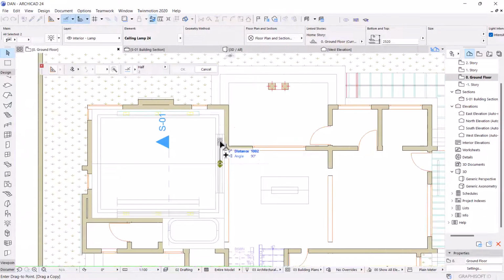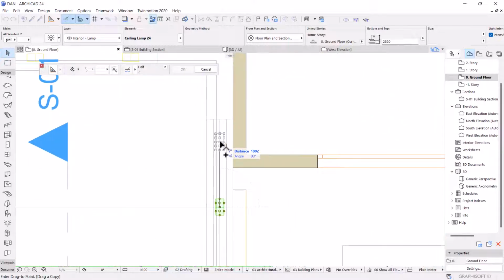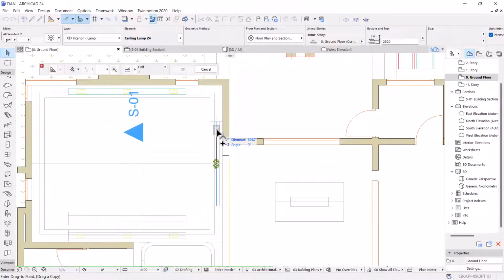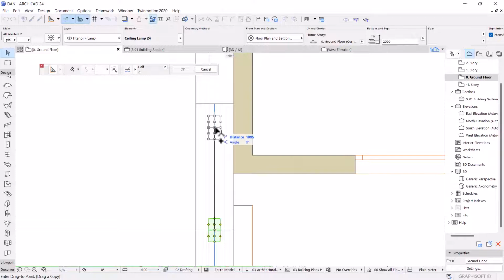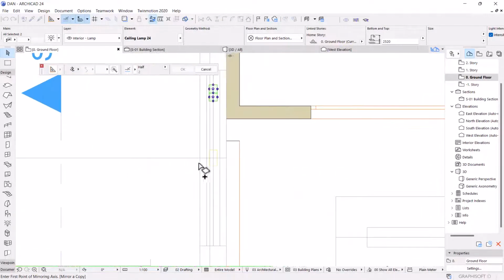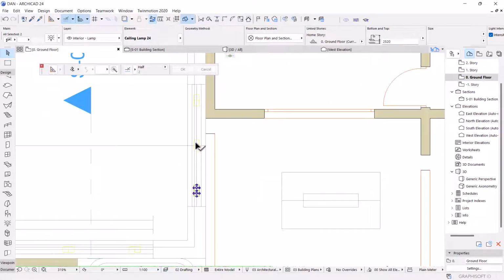So this one is not like how I did the drawing before. In the first case, I dragged this one by 1100, but now I see if I drag it by that, whatever remains on the other end is so small. So maybe drag it by 1000. Then I can mirror it, Control Shift plus M, using the center line, and I can select.